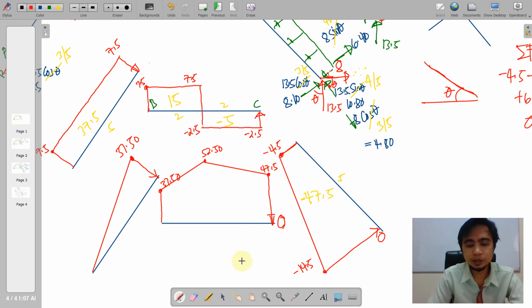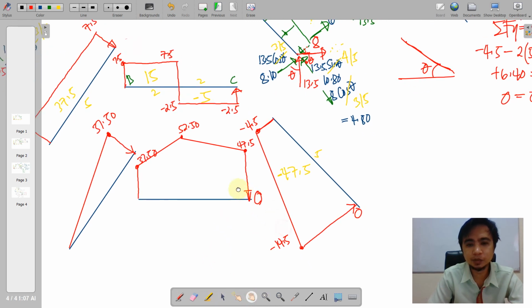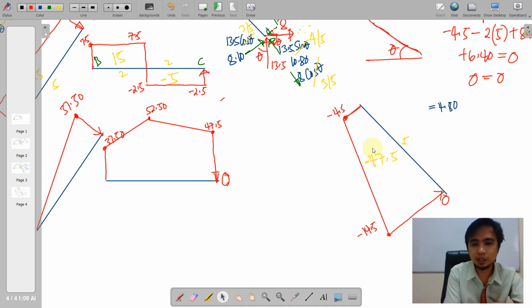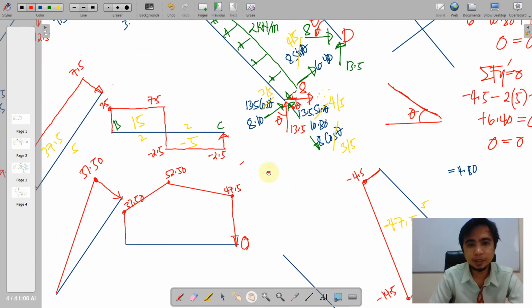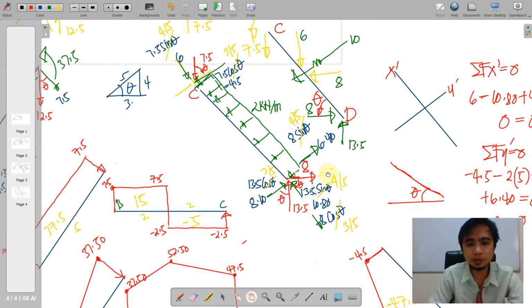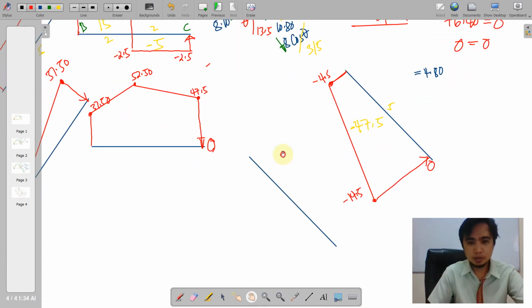Now for our shear or moment diagram based from this inclined member, perhaps we can move this in place here for a while and then proceed with the calculation. Okay, starting at your joint C. At your joint C here, we note the couple negative 47.5. Okay, although it will orient your frame outwards, that is positive, we carry again the sign. So we'll start with an ordinate of negative 47.5 at point C. Okay, so we place the value of the moment.